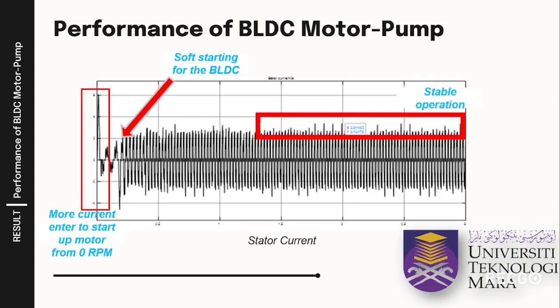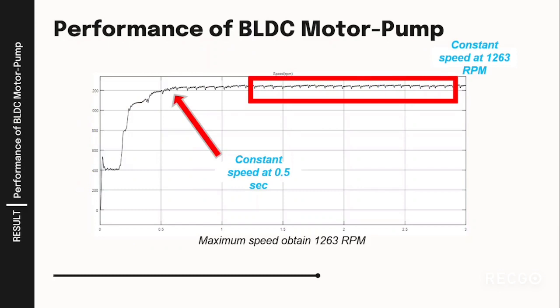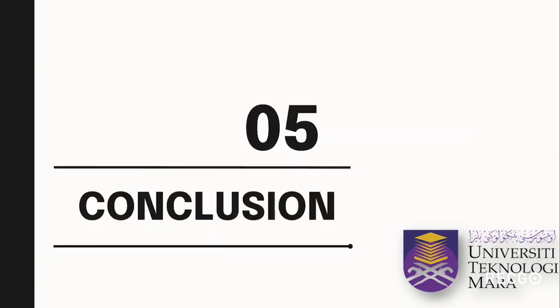The smaller pulses of the electromagnetic torque are caused by the electronic commutation of the BLDC motor. The startup current of the BLDC motor is restricted to the permitted limit, which allows the motor to start smoothly. Satisfactory for the solar power water pumping application, and analysis is done under standard environmental test conditions. It is realized that the high gain modified Zeta converter is suitable for the purpose scheme.